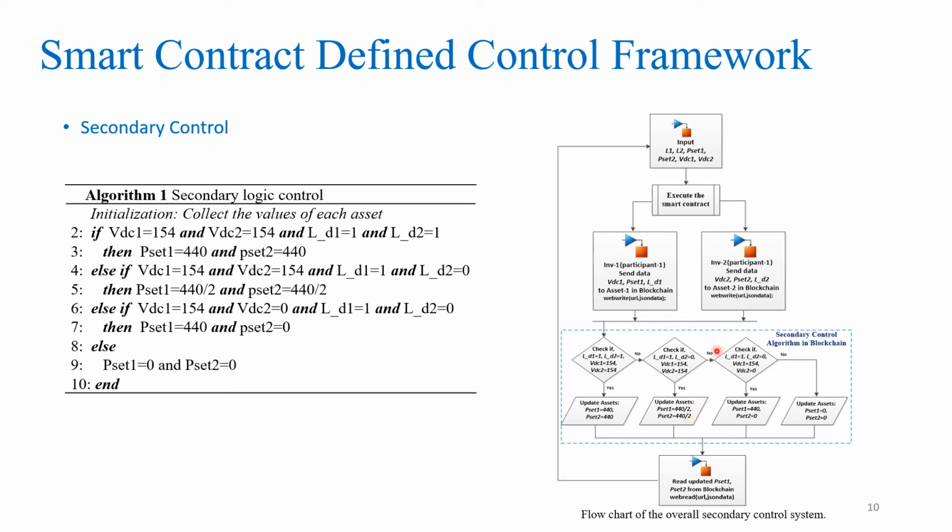The third condition is that one of the inverters is disabled and cannot supply power. In this case, we are considering that the second inverter goes down and the load demand remains the same as the second condition, which is the half load demand. Here, we want to set the active power set point for the first inverter to its maximum capacity, but the set point for the second inverter should go to 0, as it is unavailable.